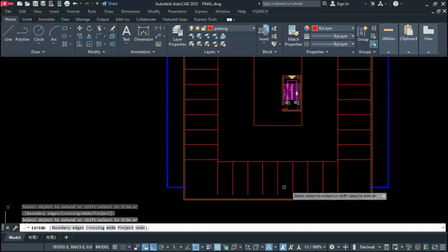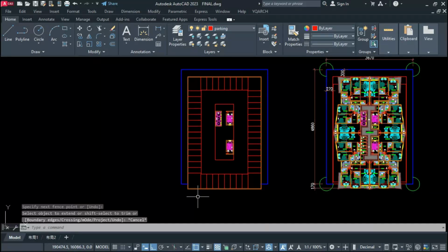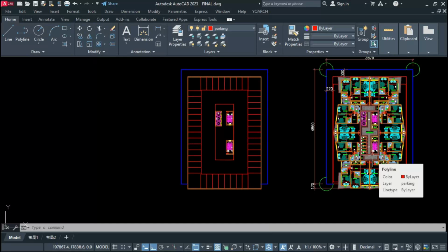So this is the rough condition for our parking layout, and we will arrange properly column layout over here as per typical area, because we have center to center lot of spacing. So we have to arrange as per parking, as per typical our column layout, okay. This part we cannot keep anything, any column layout, because it must be clear.